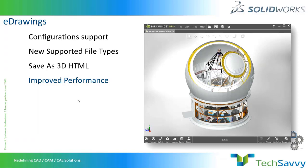Not only can you open it in this environment, you can actually revolve it, move it, rotate it in a 3D condition. Till now, if somebody has to share data from eDrawings with another person, that person needs to install the eDrawings tool on another system. Now in SolidWorks 2019, there is one more thing that we have added: we can now save the same eDrawings file into a 3D HTML document.